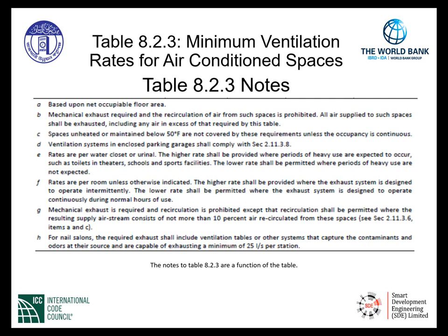For example, note H. Note H is given to us for nail salons. This is a specific requirement here, and it gives you a specific exhaust requirement in the ventilation table for nail stations, such as tables or other systems that need to provide a source capture system.